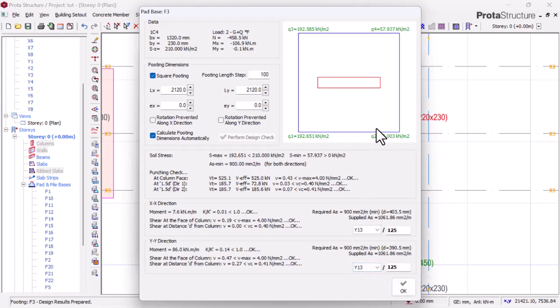So you see, there's one thing with this software. When you have a combined footing, this is how it always turns out. It gives a rectangular column instead of giving us a double column. I think the next version they bring out, maybe from 2024, they should model this. I think they're going to work on this, please. But for the time being, it's still good. It's just that the detail will show us this. So when you're doing your detailing, you just have to put the columns at the right position. That's just it. But the analysis is intact, it is all perfect and okay. So we click OK.